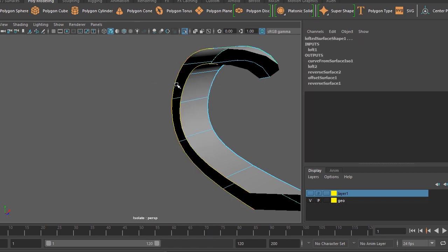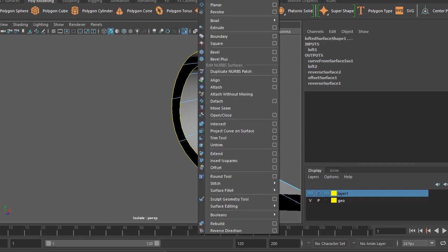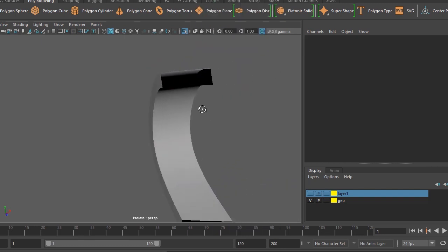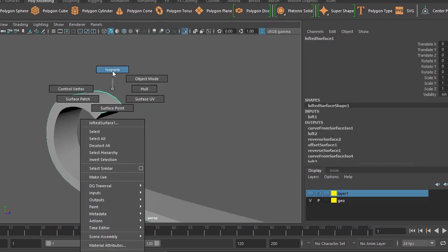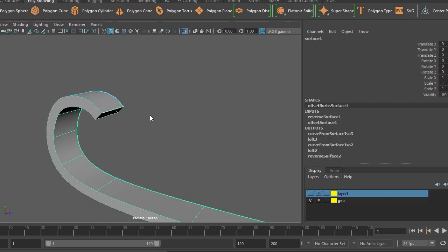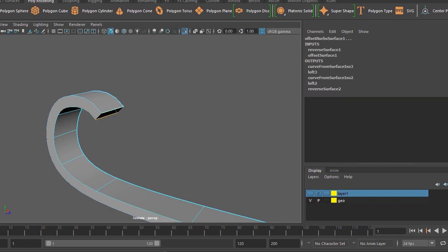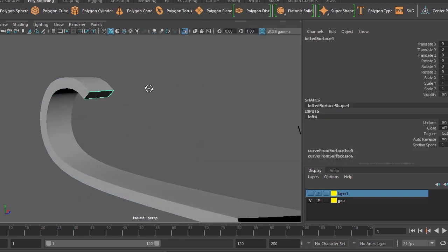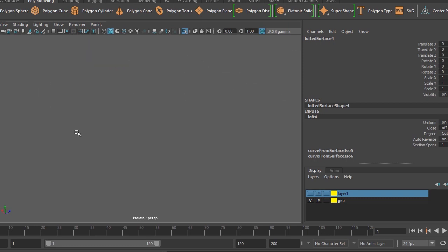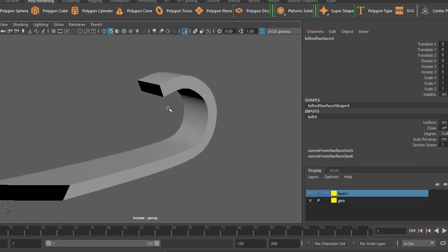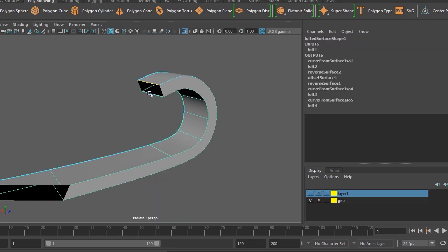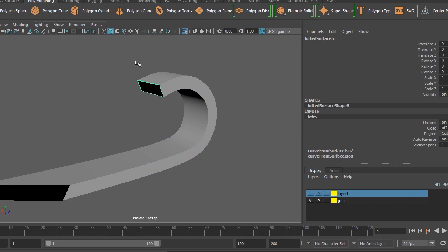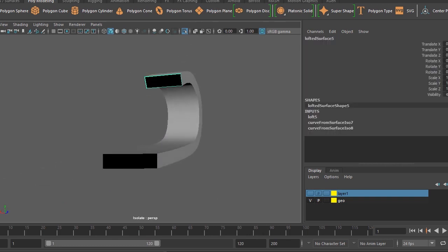So I'm selecting isoparms of both the curves, and I'm applying loft. I'm creating the geometry here, and here, right click isoparm, right click isoparm, and then a loft, and this surface normals are okay. Now isoparm, loft, normals are reverse, so I say reverse direction.